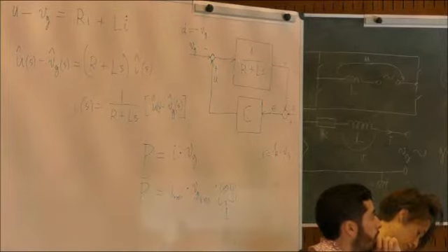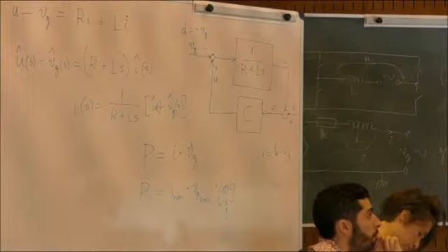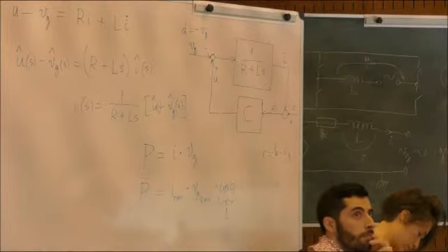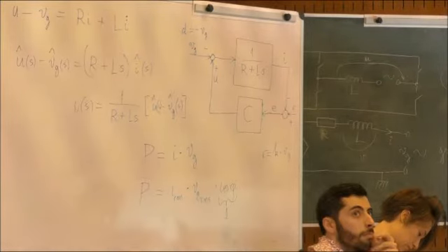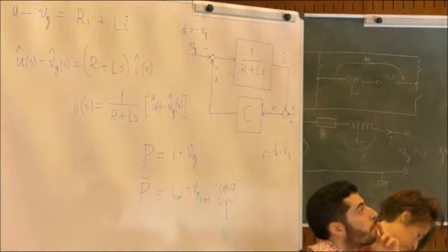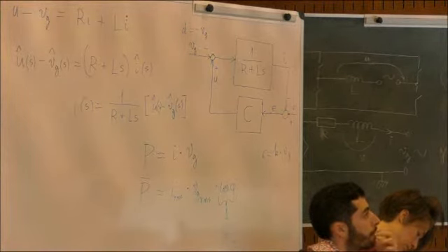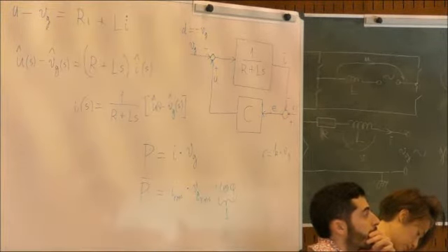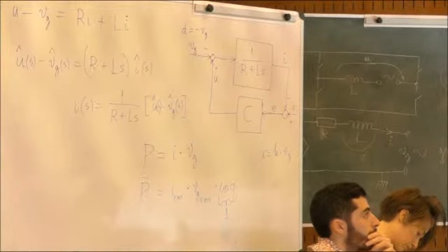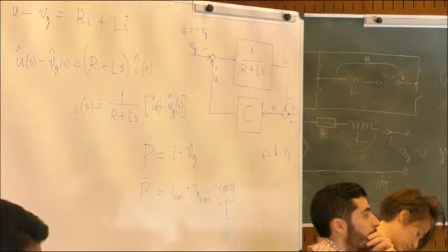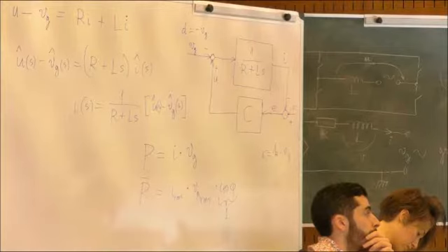And you compute the sum of the absolute value squared of all the components which are not the fundamental, divided by the sum of all the components squared. So in other words, L2 norm over one period. The L2 norm over one period is the same as the sum of all the Fourier coefficients squared.